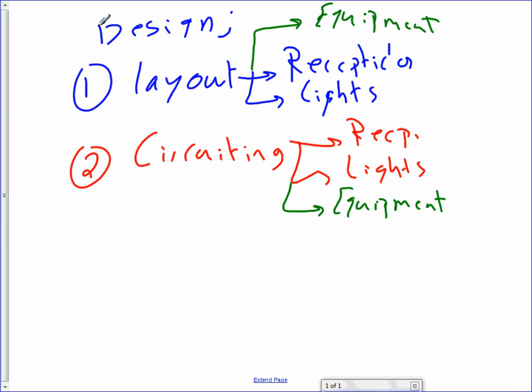Luckily, the NEC code book, guys, Article 210, not 310. When we talk about NEC 210, it will walk you through in detail where you need to put these receptacles. That's called the branch circuit. 210 in particular applies to dwellings and non-dwellings as well. In particular, for dwellings, 210.52. I'm going to write it directly, 210.52. This section, believe it or not, has a dot.